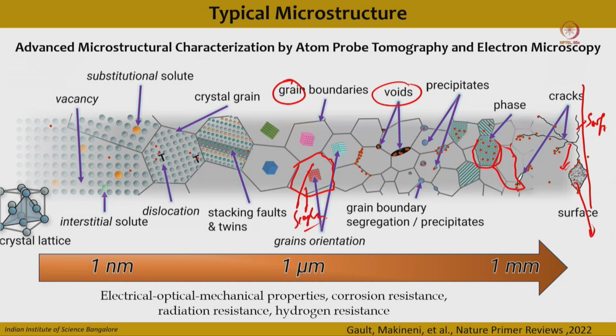And if these single crystals are arranged in a random fashion, sharing grain boundaries, it means that if you go from the first grain to the second grain, your orientation will change once you reach the second grain, and these are called grain boundaries, which enclose these grains, correct.